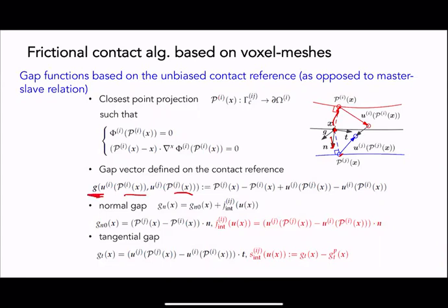The gap vector gives us the normal gap and the tangential gap, by checking from that reference point the relative positions of these two particles moving. So for each individual point, we can map it at the reference point into the corresponding upper and lower interface. If we have a point-by-point pair, we can generate the relative displacement jump between the two particles. And from the displacement jump, we can recover the traction from the corresponding Coulomb envelope constitutive law.